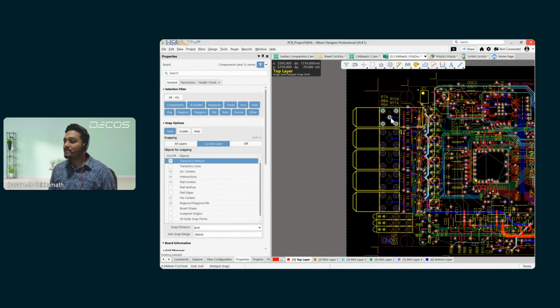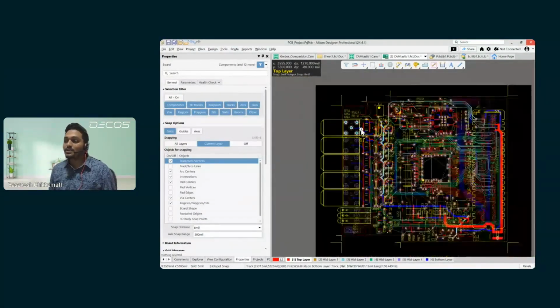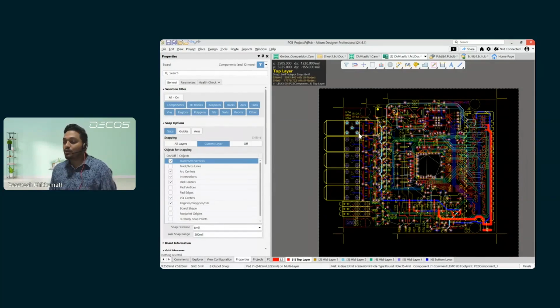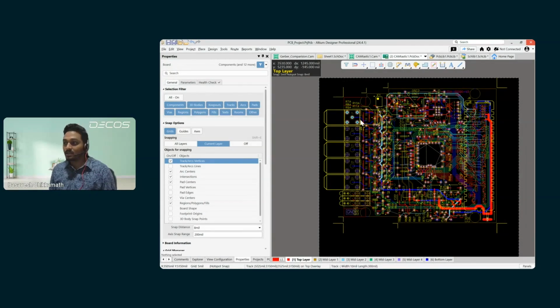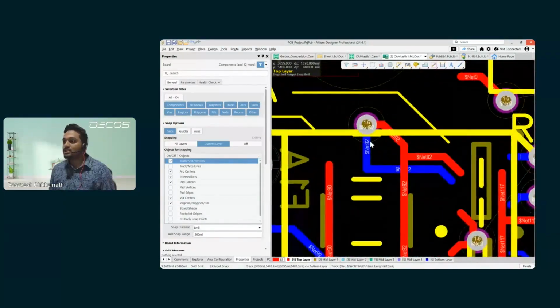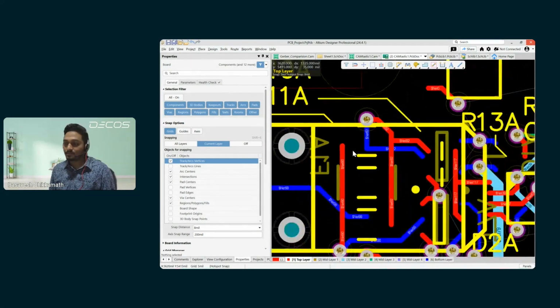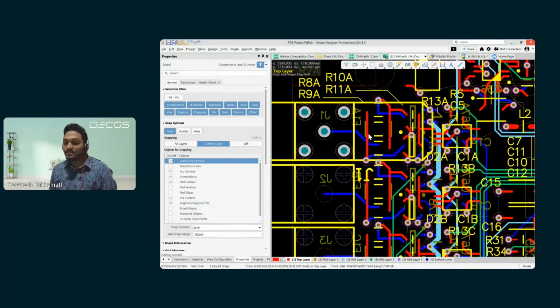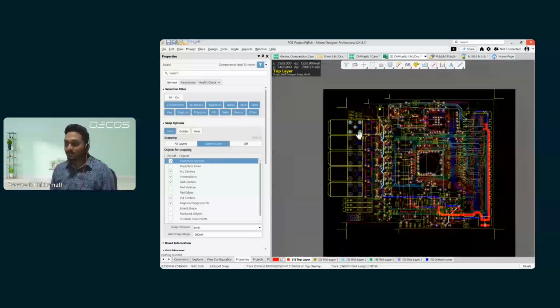As you can see, I had placed this particular connector away from its respective location. Once I imported the pick and place file, it went back to the exact same location as it was earlier. And that is how we can make sure that all the component locations and orientations match exactly. The only issue left in this particular PCB is the tool generated or CAM document generated netlist or net names. To fix this, you have to recreate the schematic and import it into this PCB.